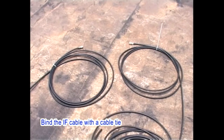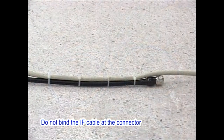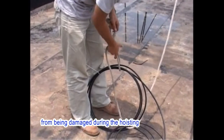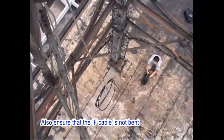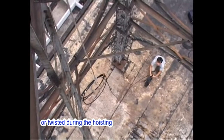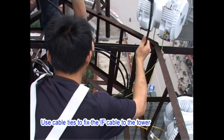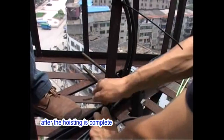Bind the IF cable with a cable tie. Do not bind the IF cable at the connector to prevent the connector from being damaged during the hoisting. Also ensure that the IF cable is not bent or twisted during the hoisting. Use cable ties to fix the IF cable to the tower after the hoisting is complete.